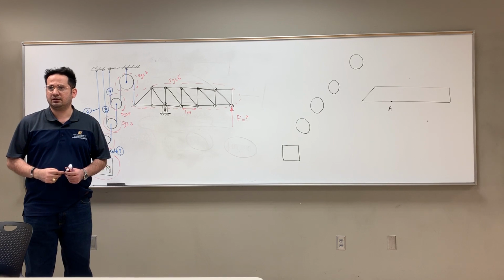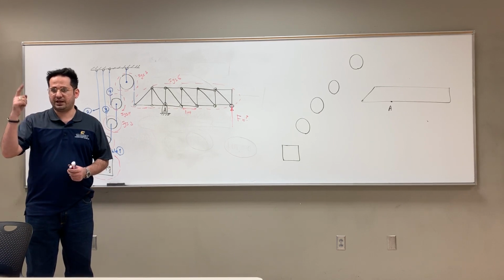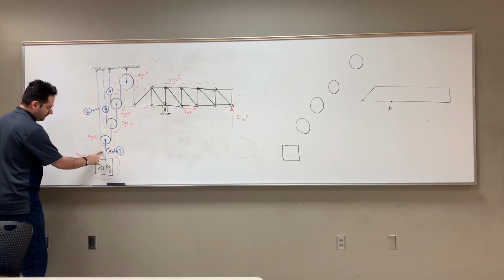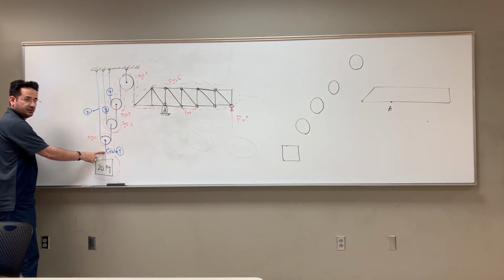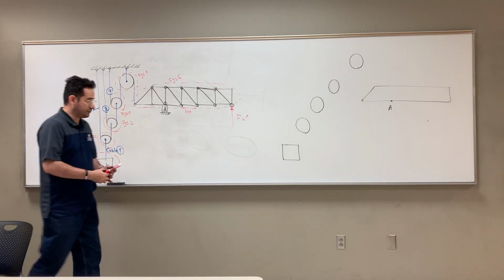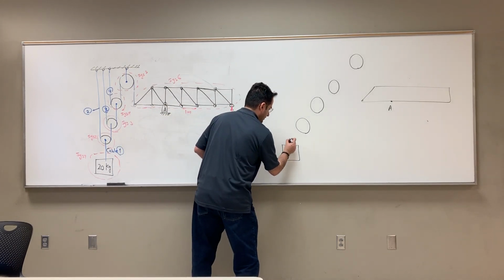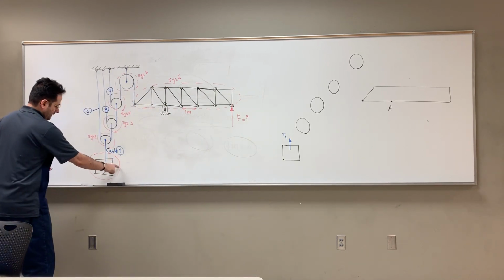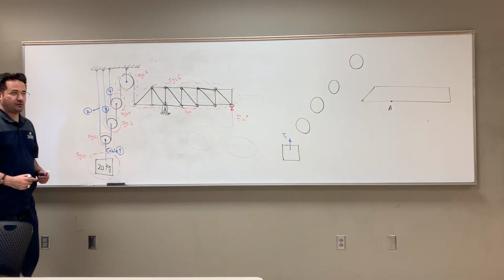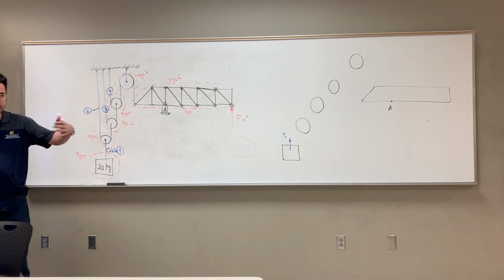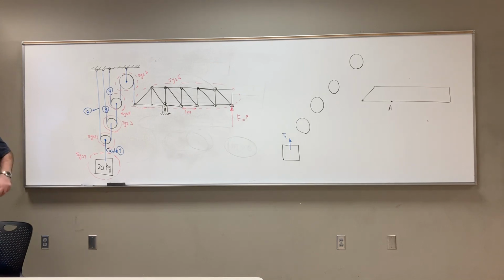Walk around to get the surface force, and then ask for body force. So let's walk around it. The only thing we call is this cable. Do I know the force on this cable? No. So you just put T1, introduce some variable. T1, unknown parameter. Now you walk around it, and that's all. This is the only interaction that this isolated system can have with the surroundings. That's the only way it can communicate with the surroundings, through this cable, right?